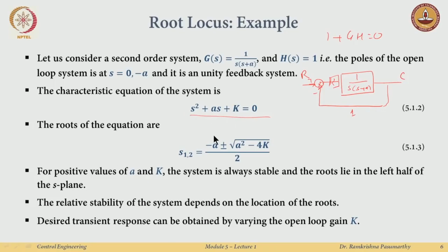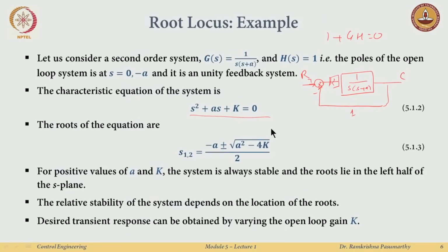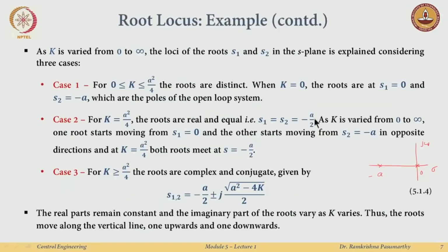Here maybe you can just trivially see that the Routh condition is satisfied. Therefore, when we were doing the second order system analysis for given zeta and omega n, which was always positive, we never worried about stability because stability was very obvious in that case. You can now see that the Routh criterion is satisfied very trivially, and therefore we were really never worried about stability.